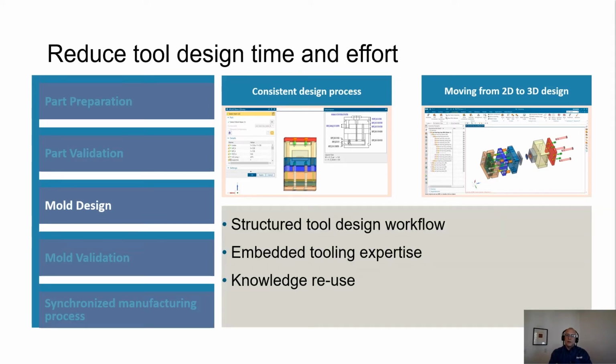NX Mold Wizard is embedded in the tools of NX, so you have all the expertise built into it. Very simple to a new user jumping into it. Again, you're just working on that top ribbon bar from left to right. So you're going to use the mold base and standard part libraries. There's a catalog inside of there that's going to allow you to just drag and drop those parts into the file. And then once you're done with it, you can generate a detailed drawing of your production parts.